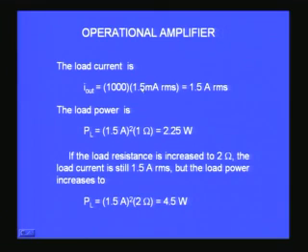So this is a power operational amplifier, it can handle higher currents, 1.5 amperes. So what is the load power? Load power is given by I square R. I square is 1.5 amperes, whole square, into RL is 1 ohm, so the total is 2.25 watts.